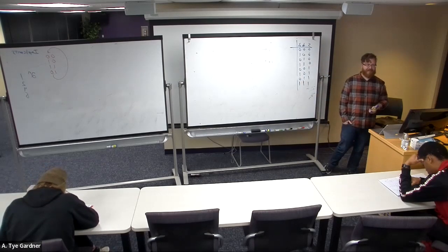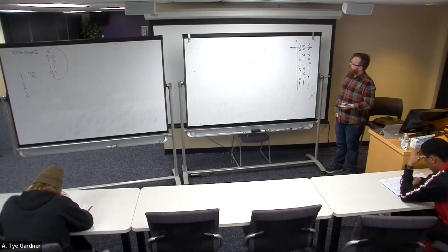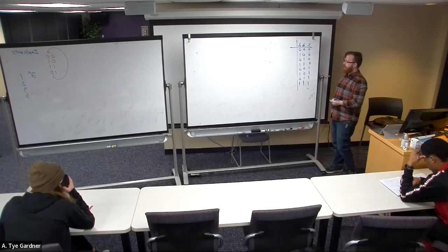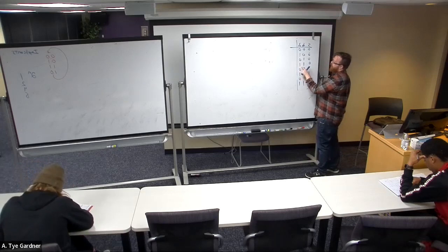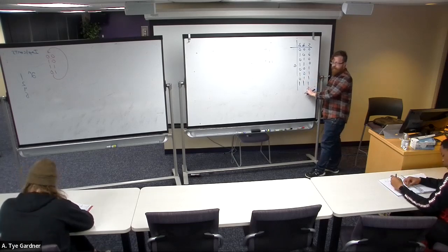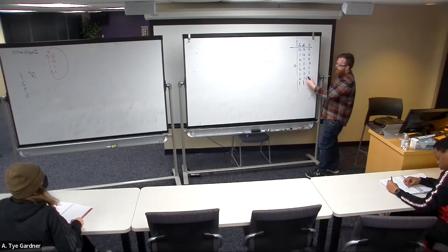Right? Senior officer, junior officer 1, junior officer 2. We want the missile to launch when the senior officer and either of the junior officers have pushed their buttons. These two are the juniors. Those are not helpful. So I know that only down here in this lower half where my senior is 1, can I possibly have a 1? And then I just look for where there are two 1s.